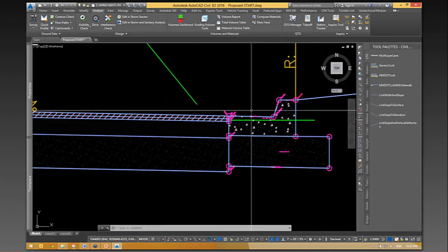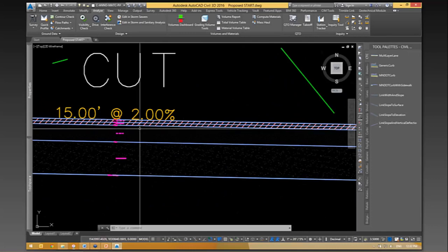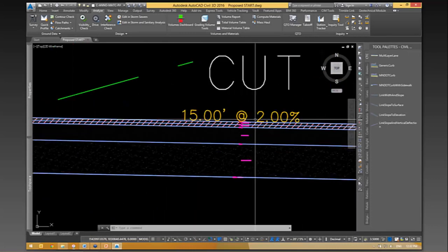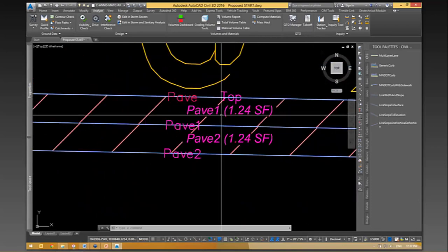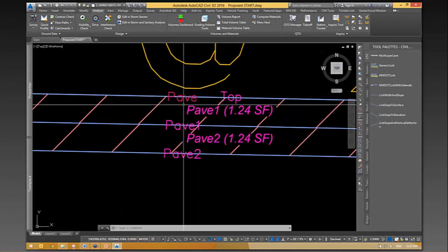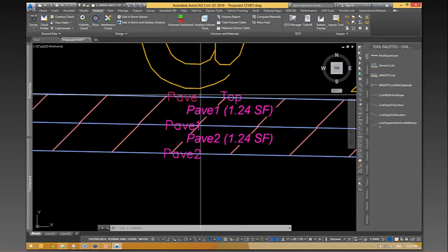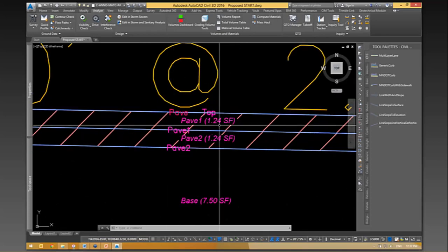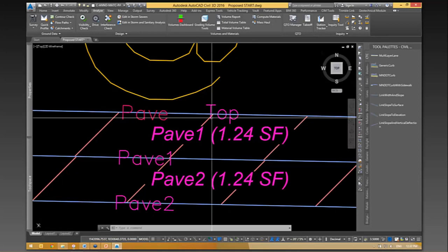And then say, for example, I also wanted to get a pavement area. I would reference a link code. For example, here I have a pave link code. The reason these are showing up, you don't get this in the out-of-the-box styles, is I just have label styles turned on in my code set style. I've actually got another YouTube webinar that gets into that in detail, so check that out if you're not familiar with how to do that.